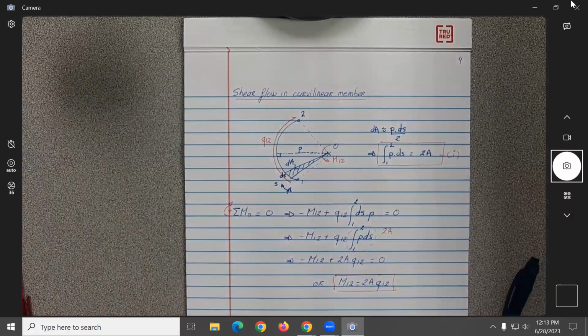So what is the reason for the next section? If you look at an aircraft, I'm sure there are some exceptions, but to give a percentage, more than 90% of all the panels are rectangular. But obviously, what happens if the panels are not perfectly rectangular? Let's say they are tapered. Then the shear flow within each one of the elements is not going to be the same.